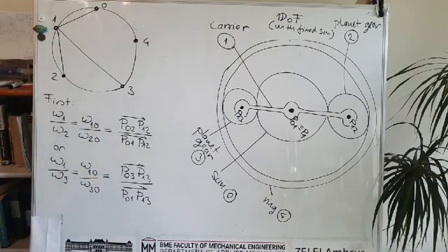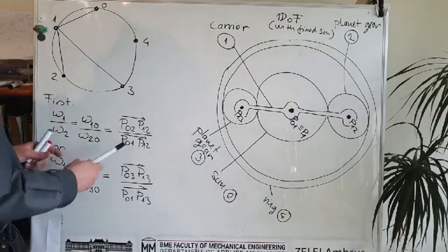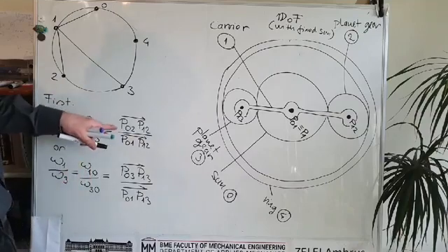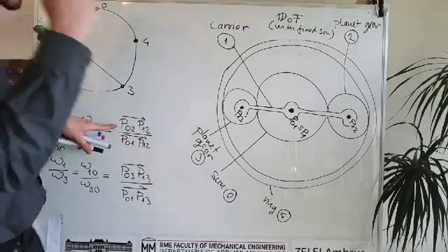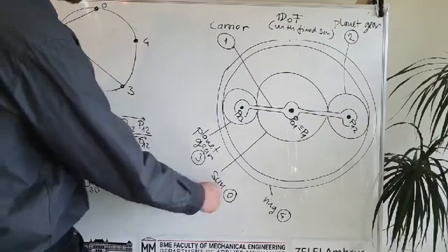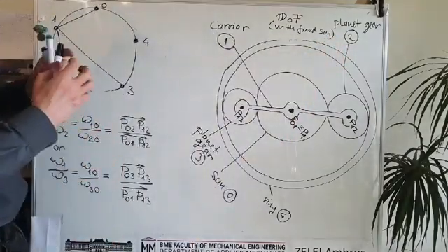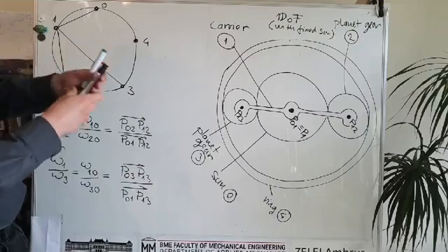P02, and P02 is also easy to find because point P02, for example, is the point where the Sun and the second planet gear have the same velocity, and trivially this is the point where they are touching each other.